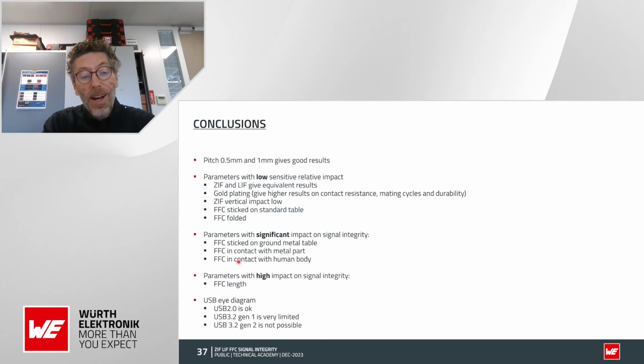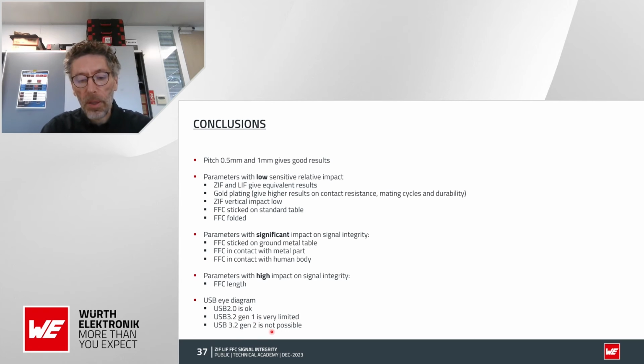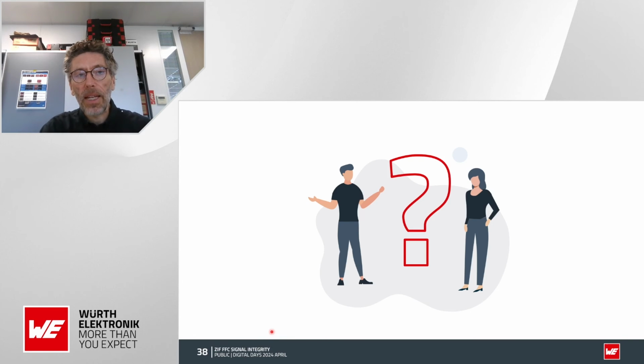And of course, what has a high impact on signal integrity is the FFC length. The connector is quite small, and what is important is to limit the impedance mismatch over a long distance. So long cables are an issue for the signal integrity. USB 2.0 is okay. USB 3.2 Gen 1 is okay up to 200 millimeters. And Gen 2 is not possible. Thank you. That's the end of the presentation.